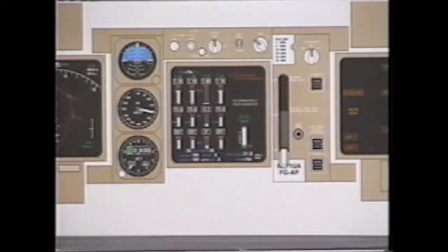If I was to push the cancel button on my ICAS control panel, the 2 amber caution and advisories would disappear. The cancel button would not cancel warnings or memos.